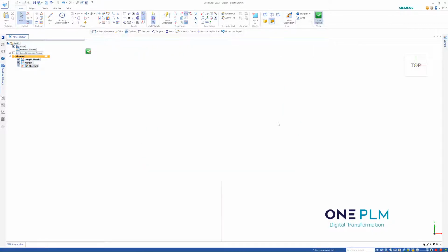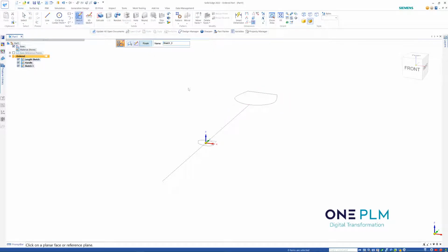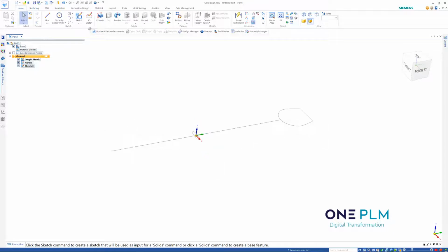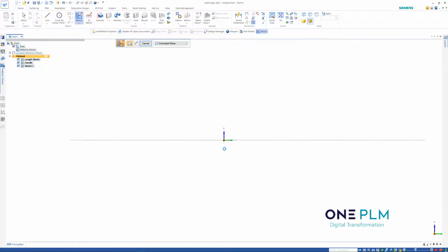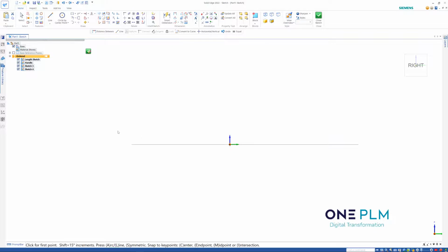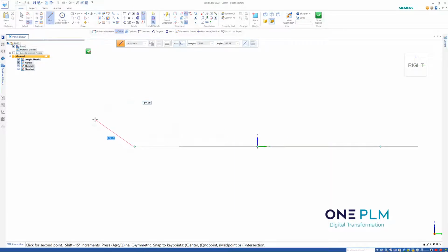So now we've got that sketch, I'm going to close that sketch and then finish. And then the next sketch we're going to put on this end, and this is going to be the revolve style section. So on here, I'm going to choose sketch, go on the YZ plane, and then to start off with, I'm going to start a line. I'm going to do a line going up from the end point of there. If you don't catch the end point, just make sure you get that end point.